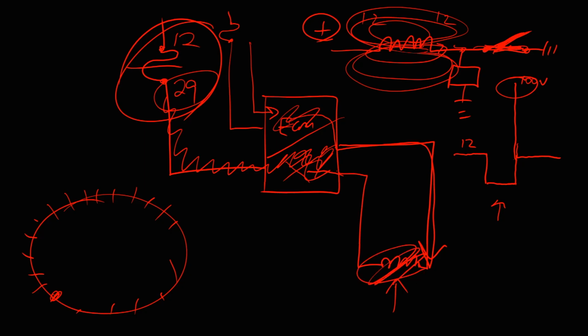And when I put my test light on it, initially it was very bright and I had 29 volts and then I remeasured and it was like 18 volts after that. And then it would slowly build back up and it was 19 and 25 and 20. It was crazy. And it was coming from the magnetic and inductive spikes of that transmission control solenoid turning on and off. That's the only explanation I can have.